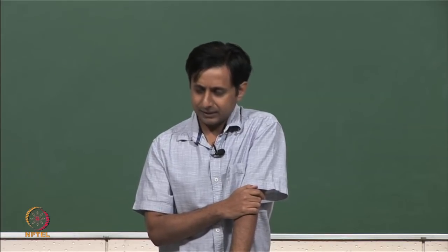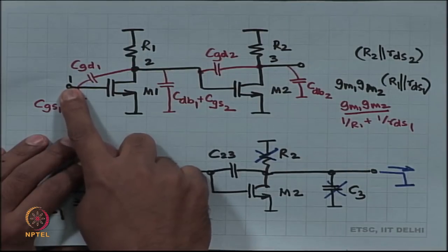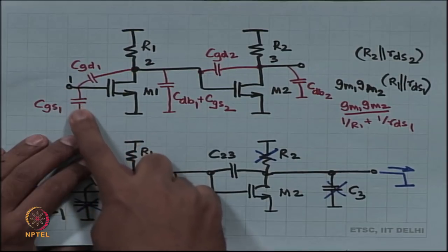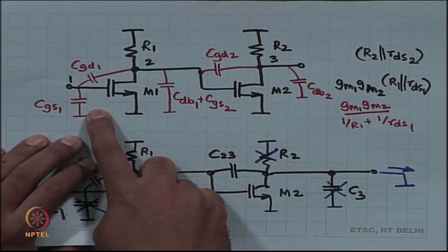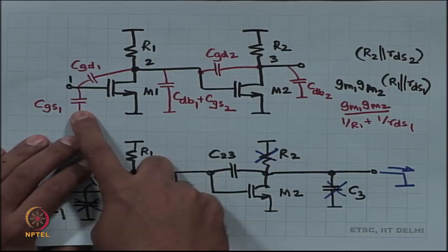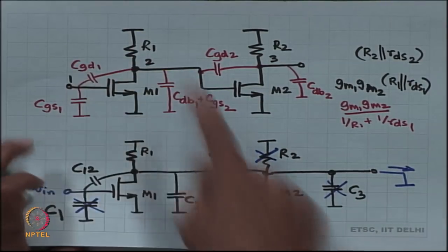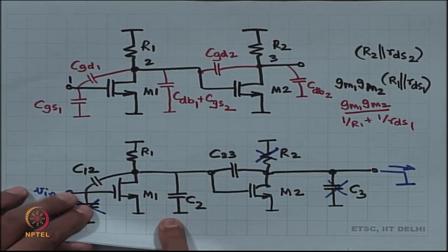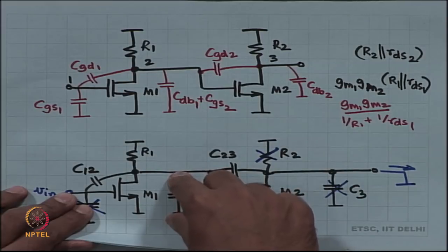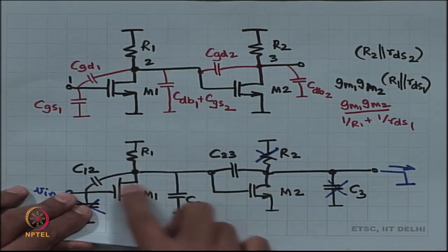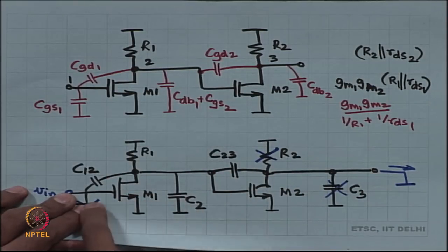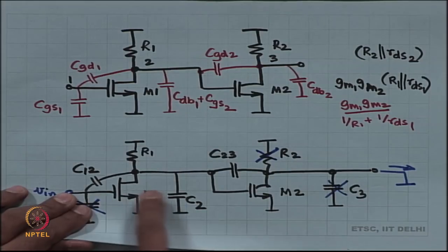So, if I try look, and what am I going to do with node 1 at that time? For the output impedance, node 1 is going to be at ground. So, for the output impedance, CGD, this C12 is going to come in shunt with C2, okay, for the output impedance. So, I have one capacitor over here R1 and GM1 is 0, right, GM1 VGS1 is 0.